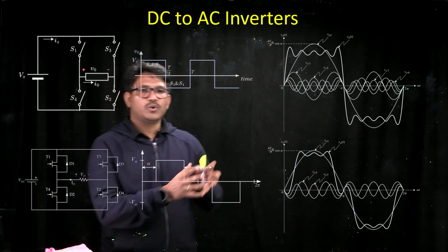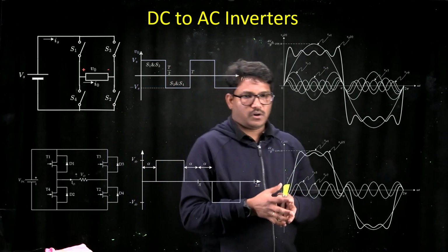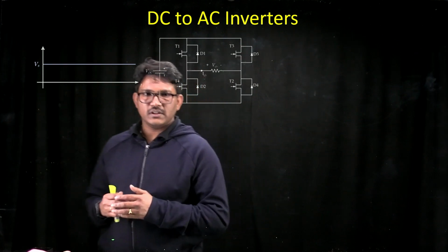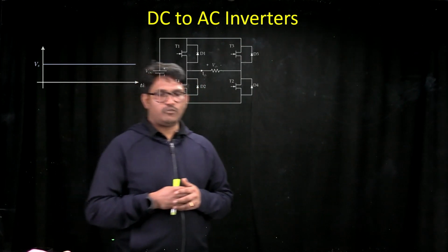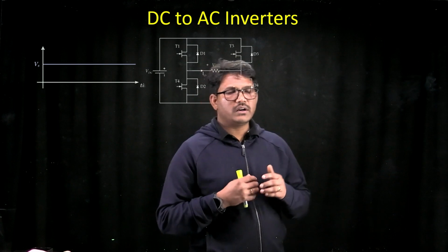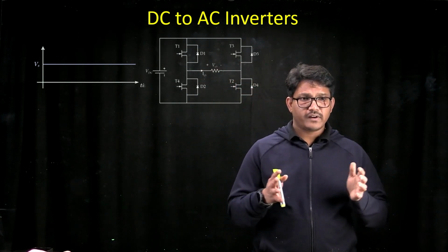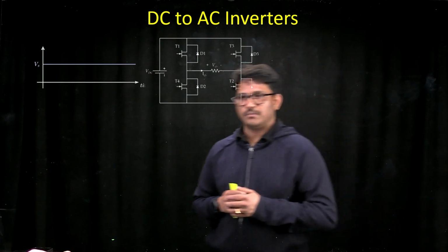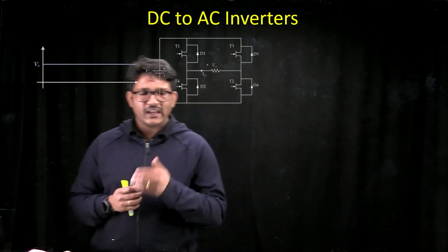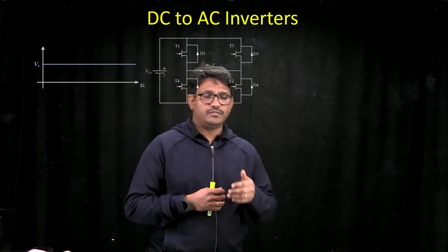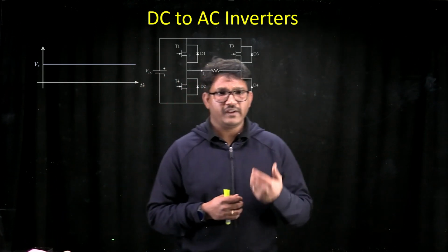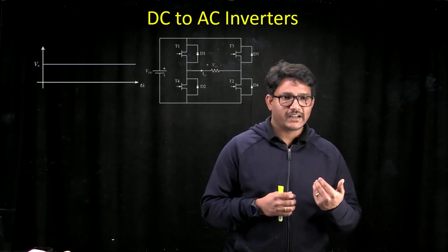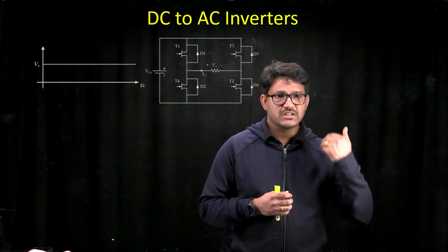This is what motivates us to go for pulse width modulation, and we have seen how we eliminate third order harmonics by adjusting the width of the output voltage. So now we wanted to know if we can have different widths of the output voltage in the conversion process, then can we eliminate the harmonics of different orders? Now, if we can eliminate harmonics of different orders, how do we select the switching sequences or switching widths